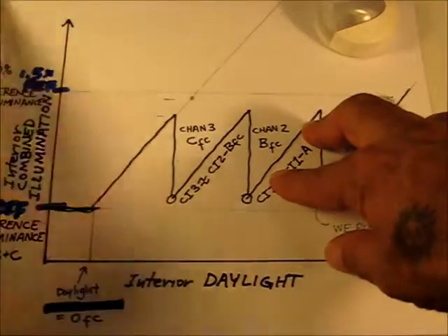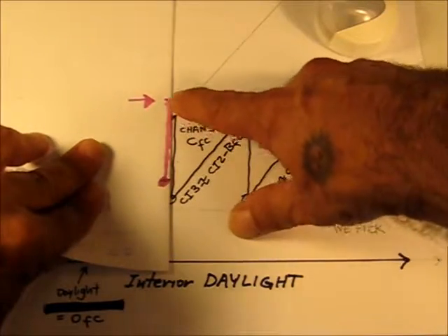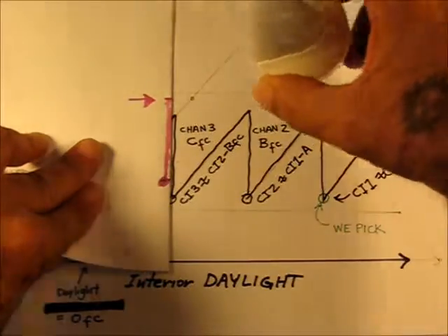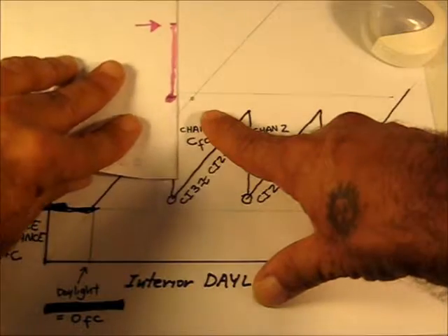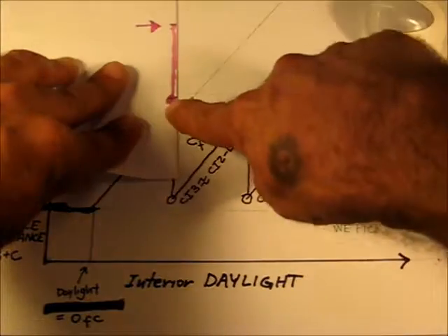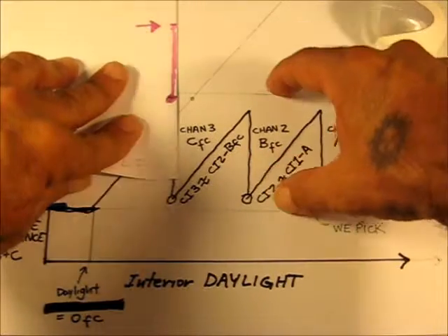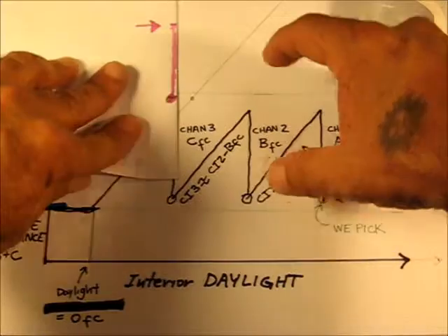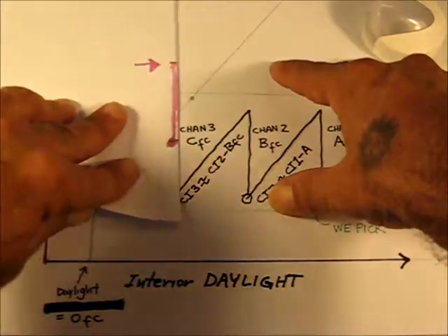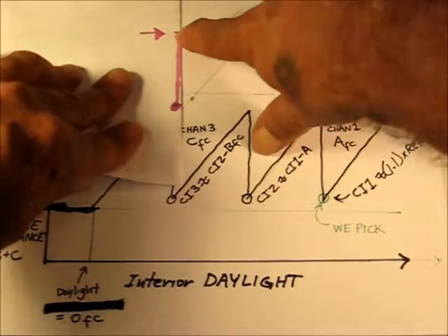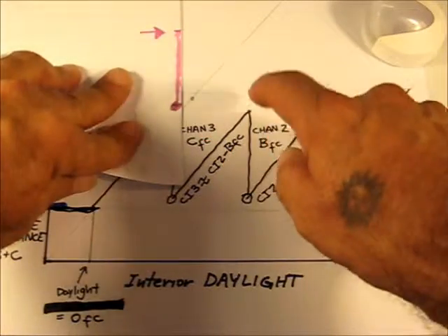So our deadband can be anywhere between the minimum that the sensor sees when a stage of lighting snaps on, and a maximum of where it drops into the zone of 1 to 1.5 times the reference illuminance. That is to make it legal in the state of California. And you can see that your cutout point can be quite high and still drop you into this zone.